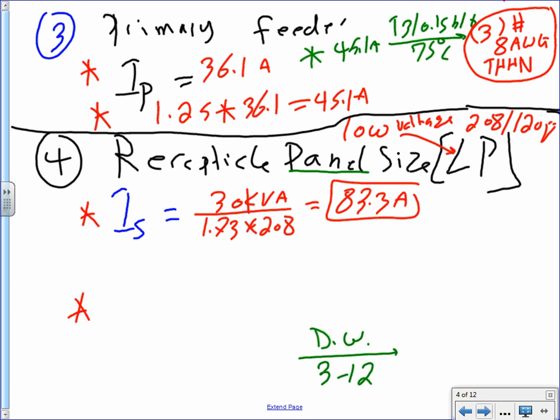The second step is, here are my amps, assuming future use, and assuming these are receptacle non-continuous loads. Typically they take this number and up it 25% for safety, future use, expansion, all this good stuff.